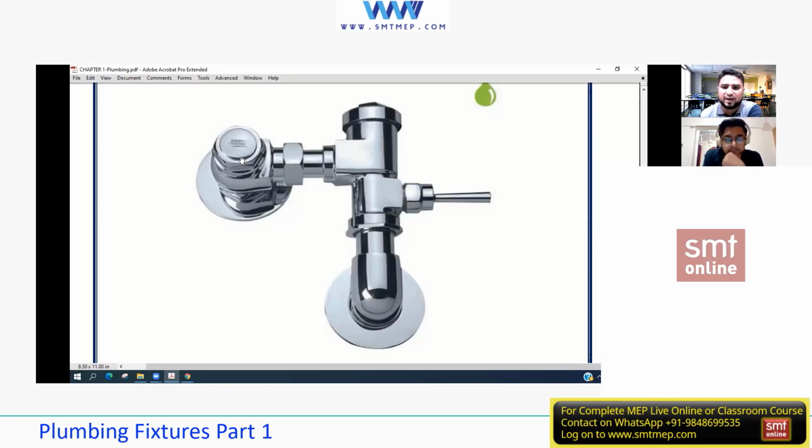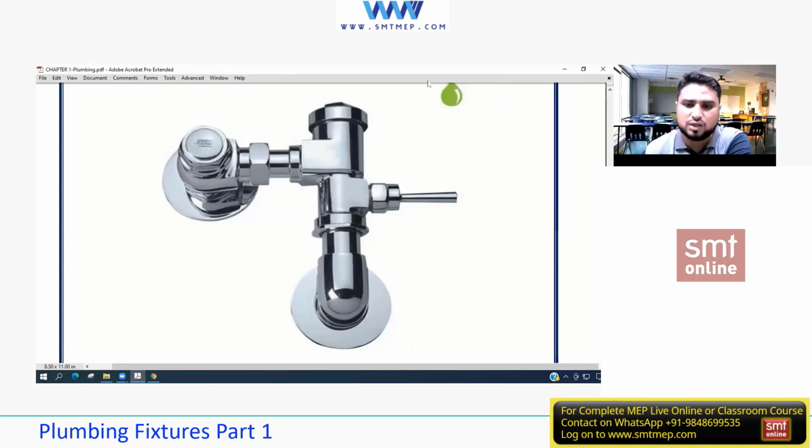But you have an idea because you have seen flushometer valves in the drawings, I guess, and the detailing. I'll show you the flushometer valve. If you want, I have some catalogs also, I can show you. But the most important point to note: there's a huge difference between a flushometer tank and a flushometer valve. The valve has 3 times more water extracted and drained out for the cleaning purpose. But you can't compare this valve with that flushometer valve. This valve is only for urinals.